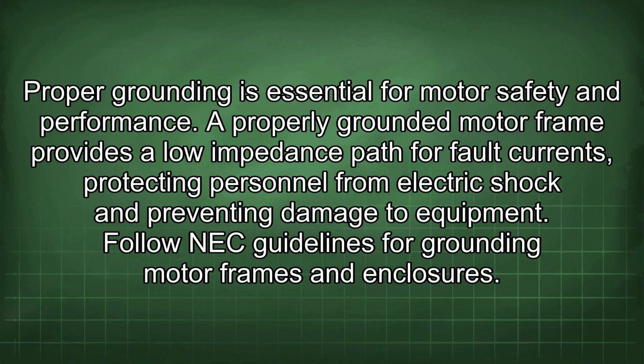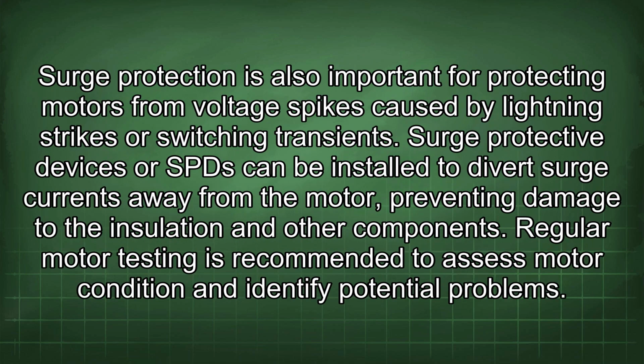Proper grounding is essential for motor safety and performance. A properly grounded motor frame provides a low impedance path for fault currents, protecting personnel from electric shock and preventing damage to equipment. Follow NEC guidelines for grounding motor frames and enclosures. Surge protection is also important for protecting motors from voltage spikes caused by lightning strikes or switching transients. Surge protective devices or SPD can be installed to divert surge currents away from the motor, preventing damage to the insulation and other components.